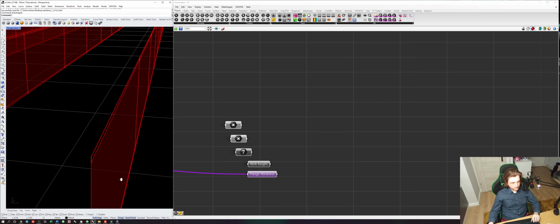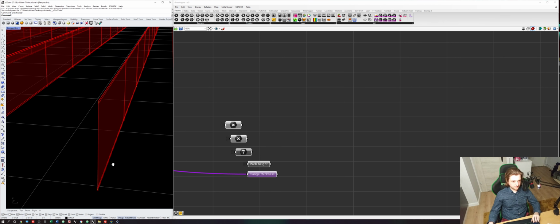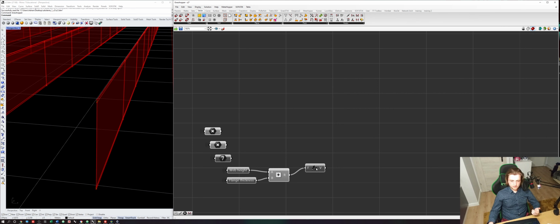So summing those two numbers together, they will give us just the flange thickness. Okay, so let's just add them. Okay, create a vector in Z direction. So go to vector Z, connect, and now go to math and add.